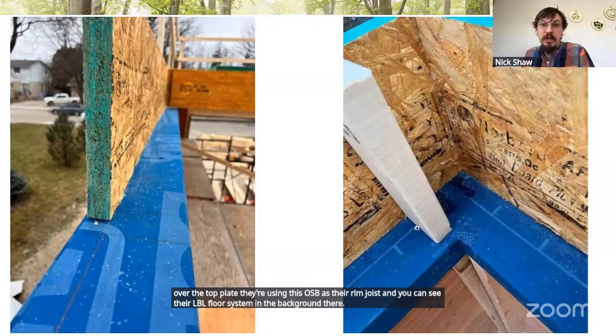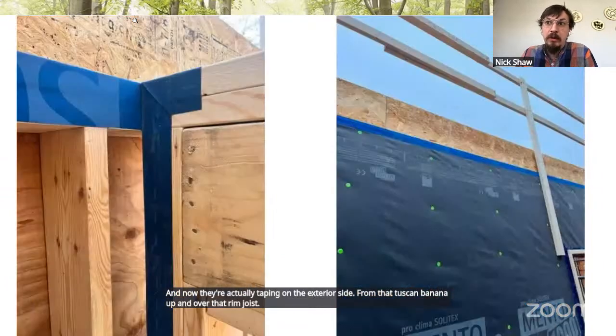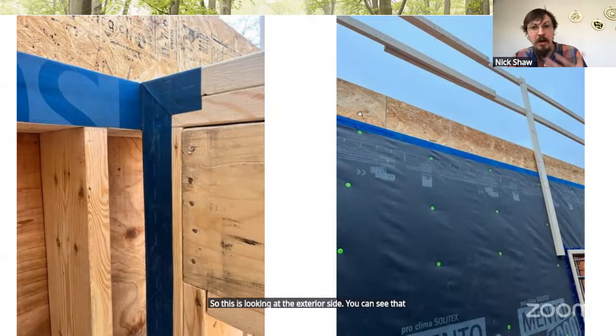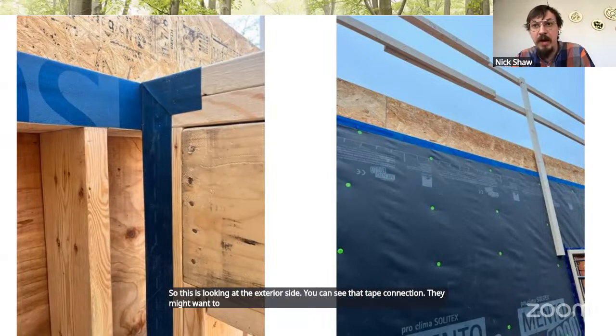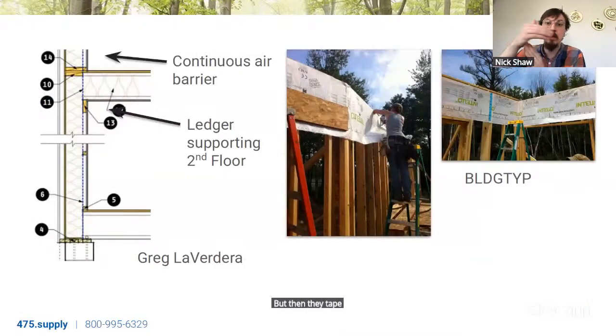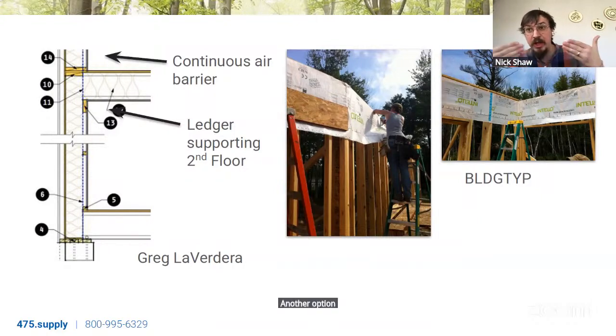And now they're actually taping on the exterior side from that Tescon Vana up and over that rim joist. So this is looking at the exterior side. You can see that tape connection. They might want to tape the seams of that rim joist, but then they tape from that rim joist in to get an interior tape connection above. Another option is just setting a complete ledger.